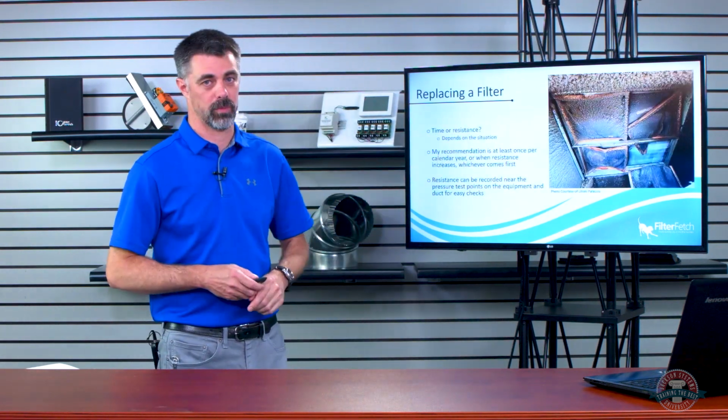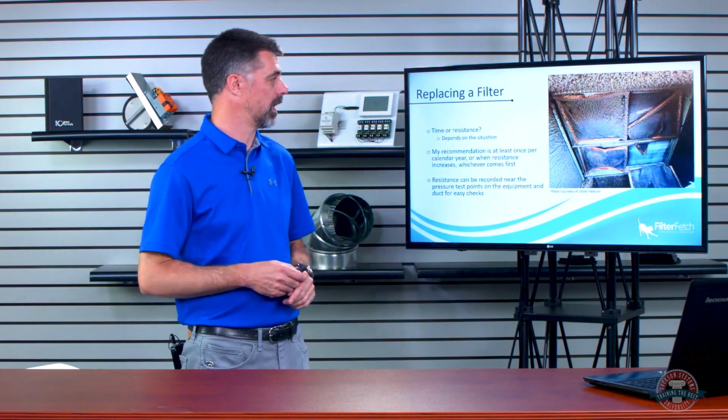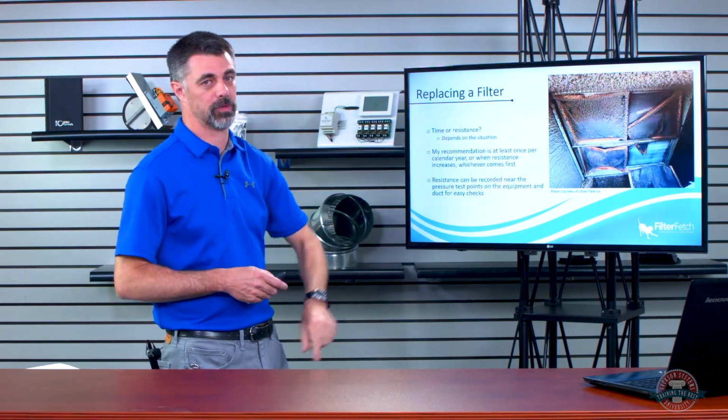When do we replace a filter? Do we do it on time or resistance? It depends on the situation. I've had filters in my own houses. In one of my houses, I could run that filter for close to 2 years before the pressure drop started increasing to the point where I needed to replace it. It really depends on the dirt load coming into the house. I like to replace it either when the pressure drop goes up or at 1 year, whichever comes first.